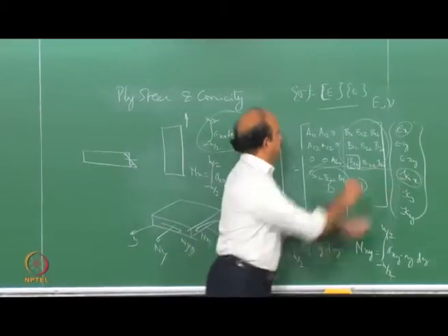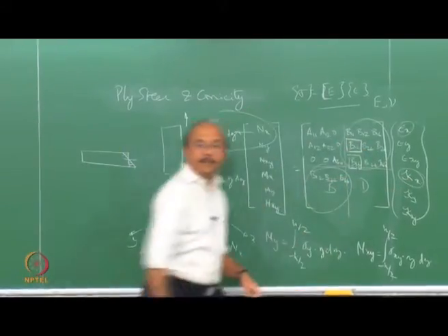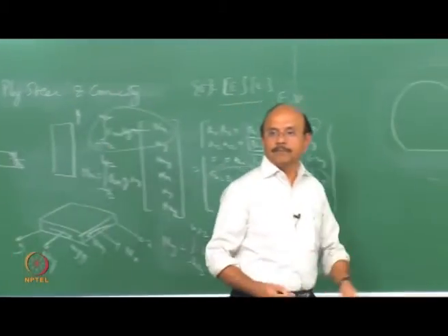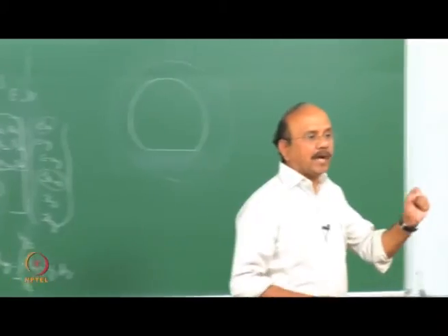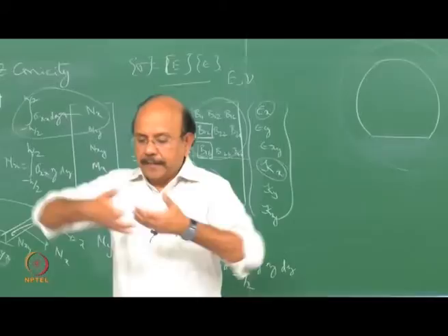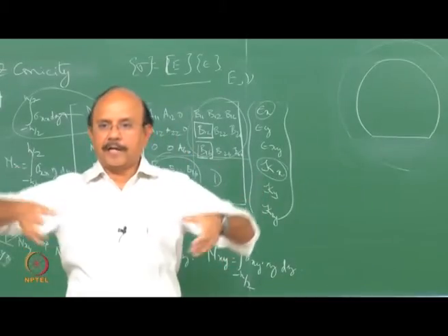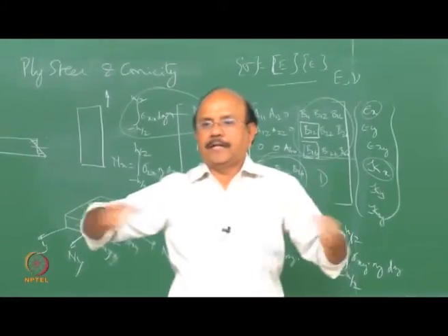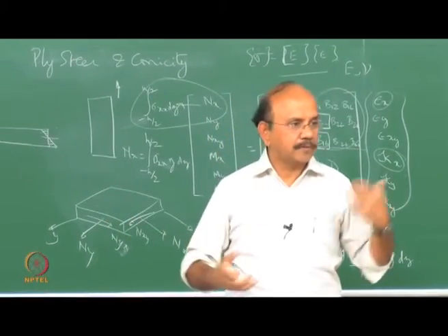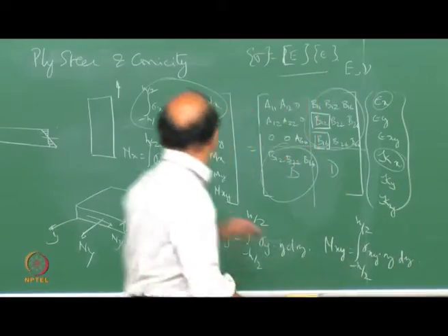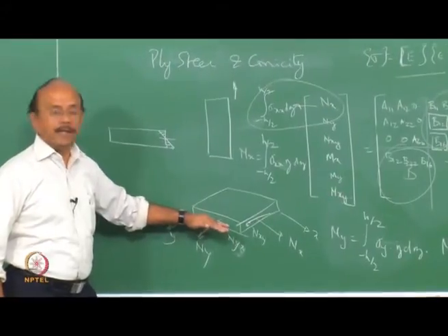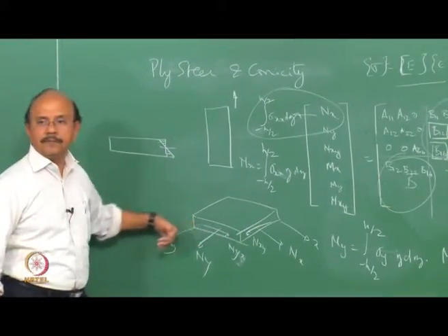Change this, here is one that is going to give me a force ny term, and so on. So when I change kappa x, it is not just a moment. You would think that, fine, I have a curvature like that, I am making it flat. How do I make it flat? Maybe give a moment like that and make it flat. But that's not just what happens. You have forces. So, in other words, I am producing a force here, and I'm producing a force in this direction.